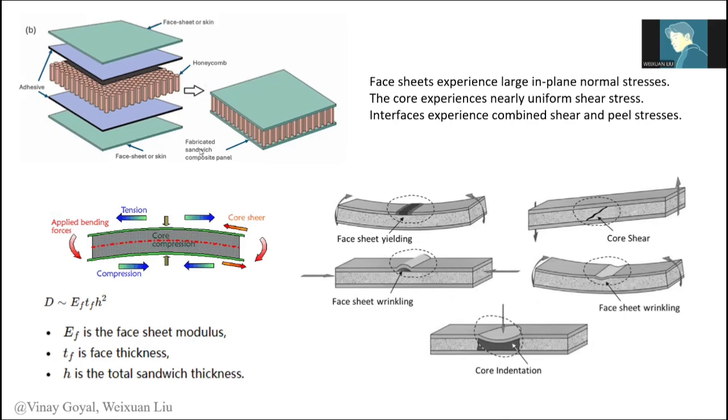With all this added together in the sandwich structure, the stress is highly localized in the skins. The core primarily acts as a shear web, and the difference directly influences the failure mechanism.